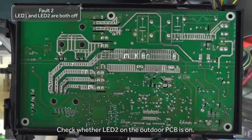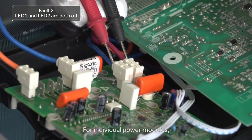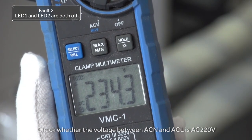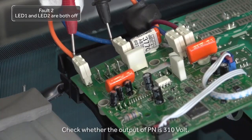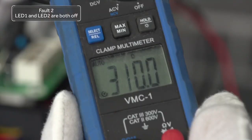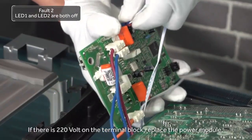Check whether LED 2 on the outdoor PCB is on. For individual power modules, check whether the voltage between ACN and ACL is AC 220 volt. Check whether the output of PN is 310 volt. If there is 220 volt on the terminal block, replace the power module.